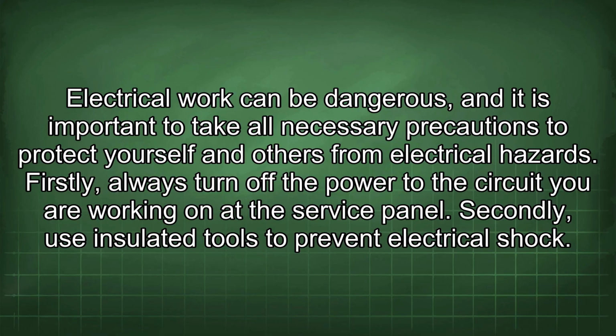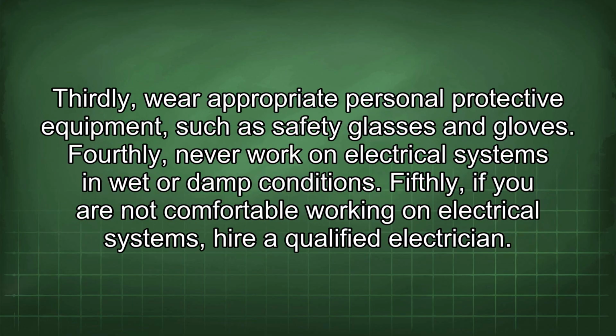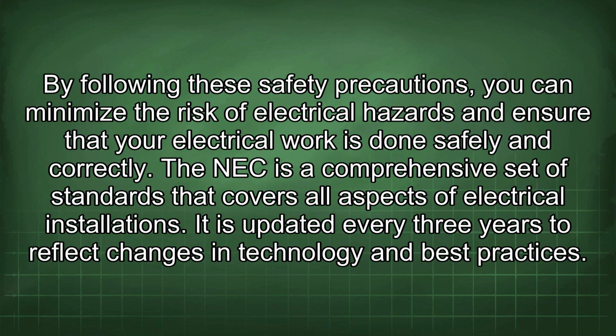Electrical work can be dangerous, and it is important to take all necessary precautions to protect yourself and others from electrical hazards. Firstly, always turn off the power to the circuit you are working on at the service panel. Secondly, use insulated tools to prevent electrical shock. Thirdly, wear appropriate personal protective equipment, such as safety glasses and gloves. Fourthly, never work on electrical systems in wet or damp conditions. Fifthly, if you are not comfortable working on electrical systems, hire a qualified electrician.